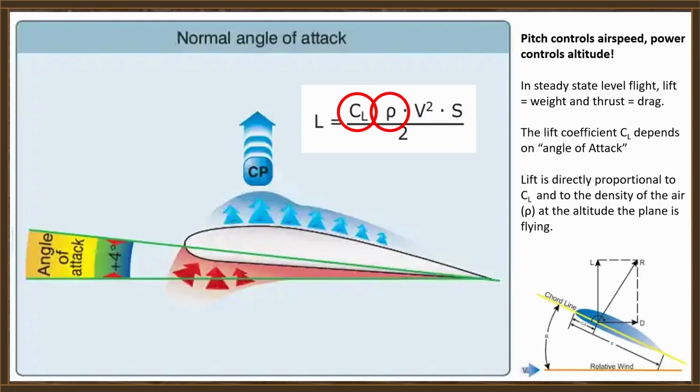Our atmosphere has a pressure and density gradient, and we all know that. Atmospheric pressure and the density of the atmosphere decrease as we go up in altitude. That means, for a fixed angle of attack, a wing at lower altitude will produce more lift than the same wing at the same angle of attack at a higher altitude. By the way, that area of high pressure under the wing and low pressure over the wing are areas of gas pressure without a container.